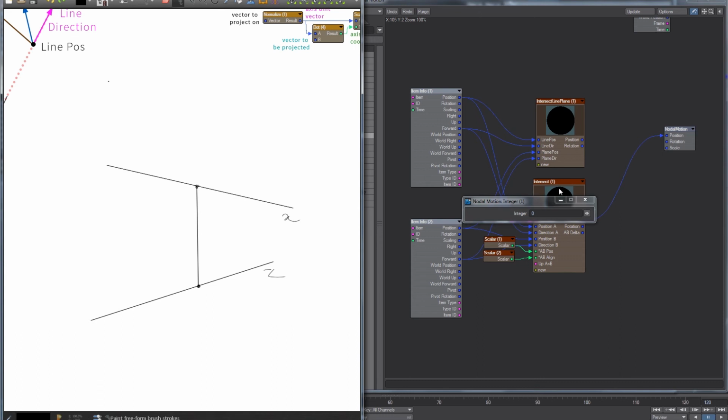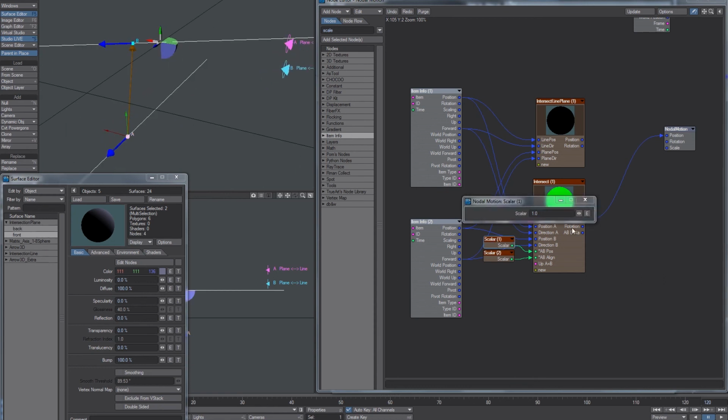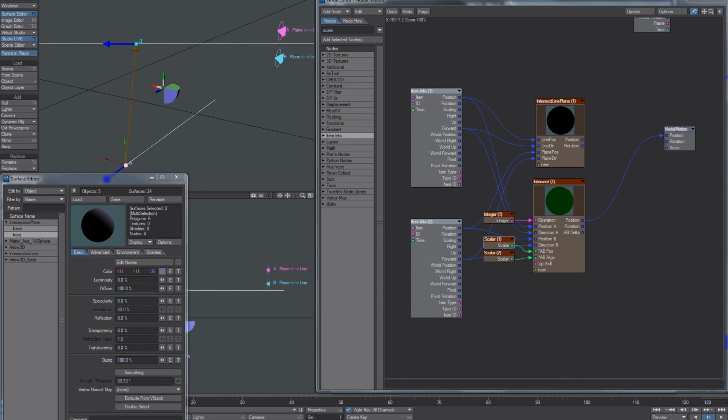And so this is what the AB position means: I'm going to decide, along this vector here, what is going to be my position. In this case, I have it set to 0. So basically it means it's going to stay on the position that belongs to A. If I set it to 1, it's going into the position that belongs to B. If I set it to 0.5, which is actually the default value, so this port here has a default value, it's going to be something in between.